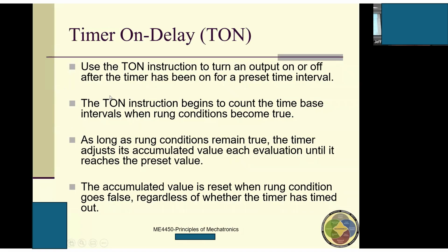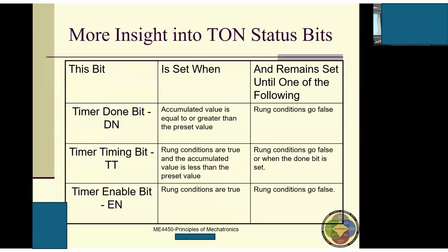Okay, I want you guys to pay attention to how the TON instruction is triggered. It is triggered by the transition, the false to true transition. Now, more insight into the TON status bits. The bit is set to one and remains set.